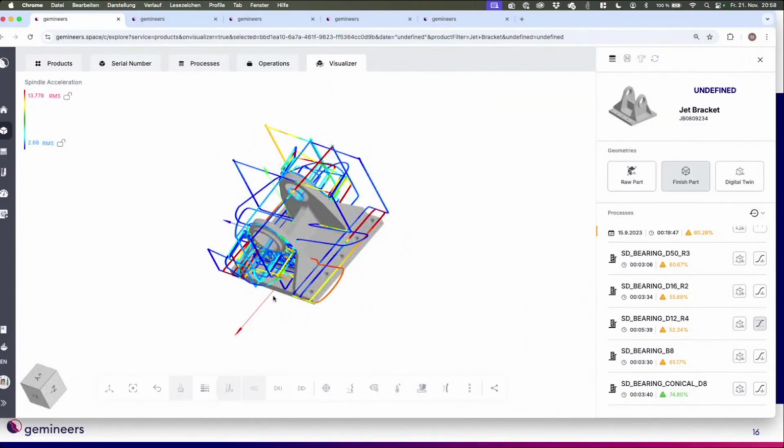Some machine tool providers already have them as a standard in the machine tool, but you can also put in an additional sensor. We connect the data, like an accelerometer, something along those lines. Yeah, we can add it, and it helps to give more insight into the process. The closer you get to the real process, the better in the end. Yeah, absolutely.